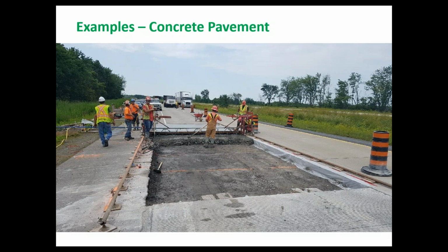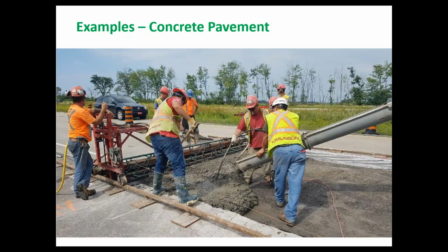So they started using the maturity sensors in this pavement repair, and they were able to monitor strengths in real time and open the lanes to traffic much more quickly. And obviously the MTO in this particular case was very happy to avoid congestion and traffic on the highway. And this is another example. In this case, they didn't have rebar, so these sensors that are typically twisted and tied around the rebar, in these cases, they put them on the dowels in the pavement.